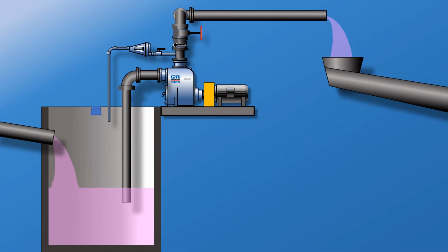And when that level starts to rise, a signal is sent to a PLC or directly to a VFD, and it tells the pump motor to start speeding up. And therefore, we're pacing the wet well. We're trying to keep that wet well to the same level, and therefore even out our peaks of inflow.